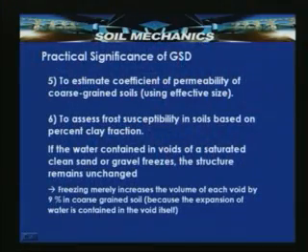The reason for this phenomenon is that whenever the water in the voids within the sand is frozen, if the water contained in the voids of a saturated clean sand or gravel freezes, the structure remains unchanged, because there will not be much expansion, because freezing merely increases the volume of each void by 9% in coarse grained soil.